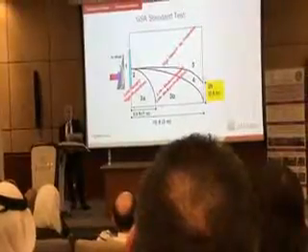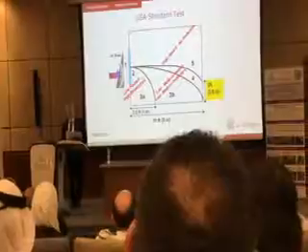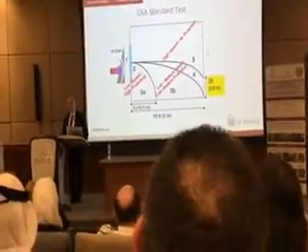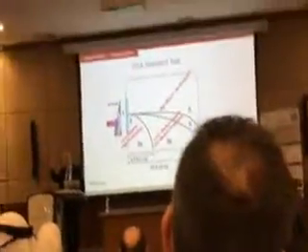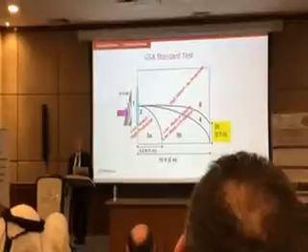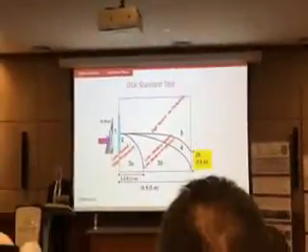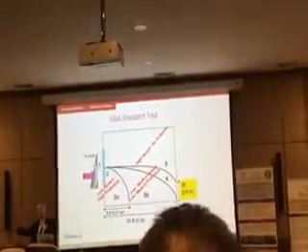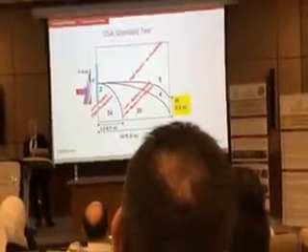If it goes past this 3-meter distance, and this is a witness panel, it's a styrofoam wall, and those glass fragments go and get stuck on the styrofoam, and you have to weigh them. There's a procedure. It's level 4, and then level 5 is high hazard. So depending on the projectiles, how far glass fragments go, windows are quantified for certain performance levels.